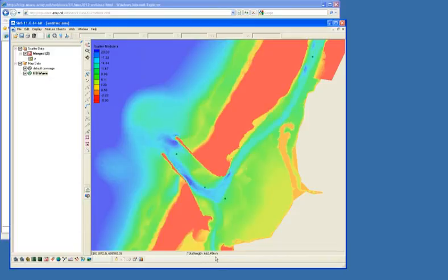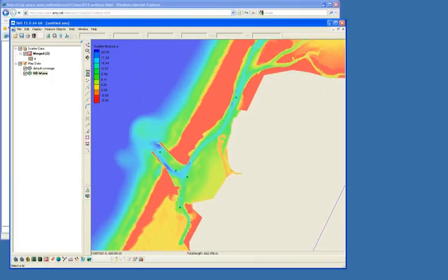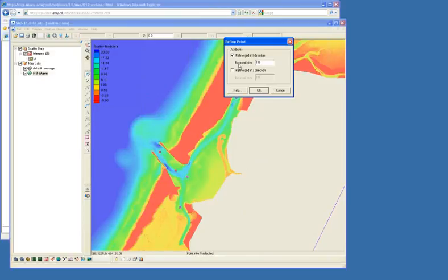That's pretty wide. So let's make about 30 meter cells across this wave. It could be probably a little bit larger. So let me reselect these points. Right click, set the node attributes, and we're going to choose 30 meter spacing.